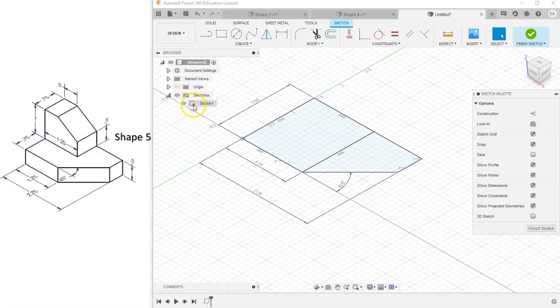And if you look, we have this fully constrained sketch. It even has this red lock on it. And you might be thinking to yourself, well, Mr. Anderson, okay, this is a fully constrained sketch, but it's actually two shapes. I want it to be one shape. And we could use the trim tool and trim this off if we wanted to.